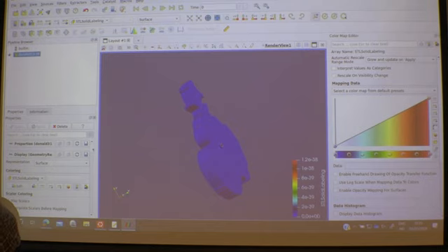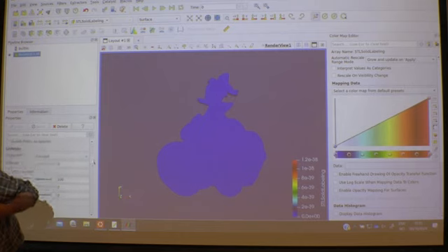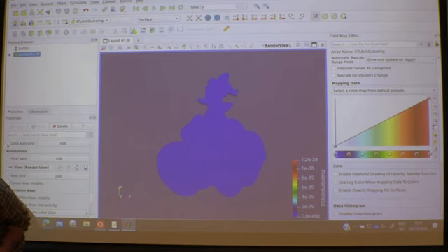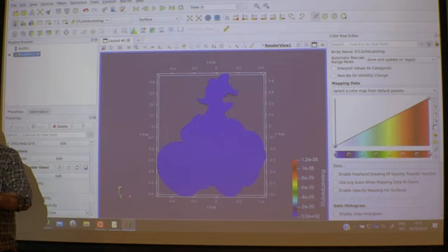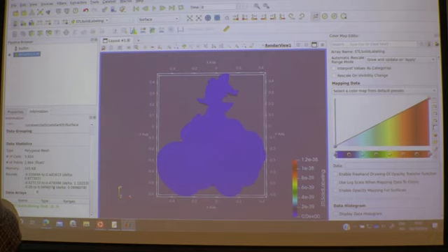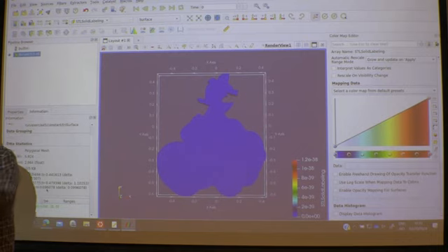I mean, you should get the information here. Let's see. If you go down here somewhere, you can put on the data access grid. So you get the size. And there also, you should get the information. So here you see the delta set go from, say, -5 centimeters to +5 centimeters. That is the STL file. Hence, your background mesh should then be narrower than that. So say ±3 centimeters, something like that.